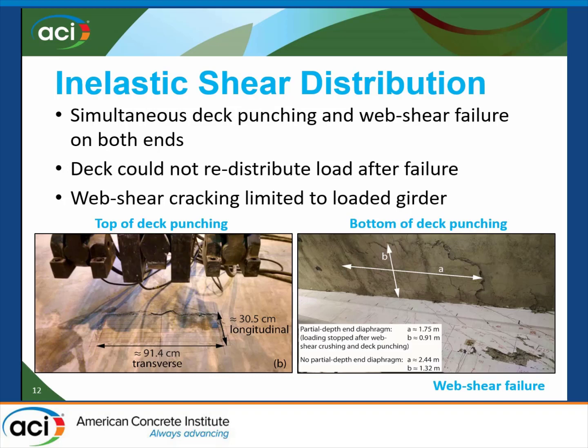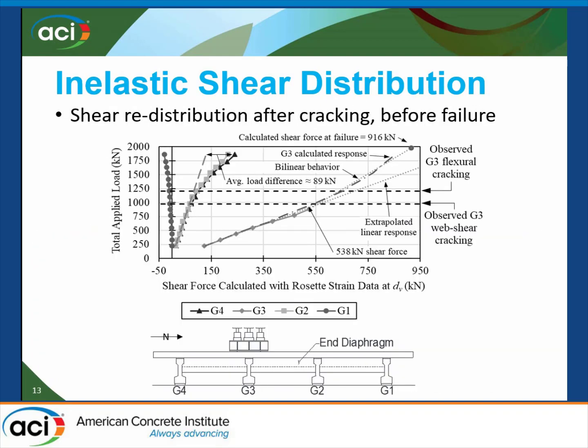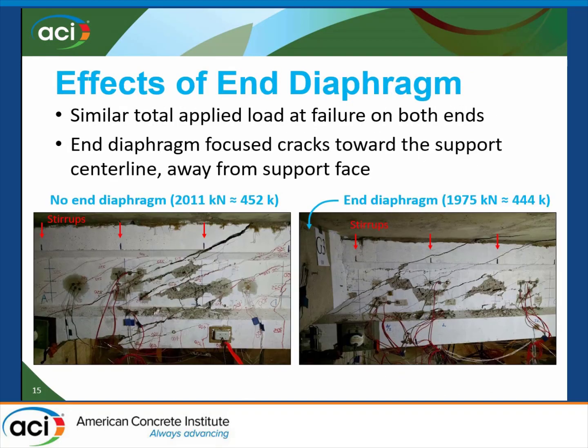So to follow up on that, how do these loads compare to the actual wheel loads that would be applied to a bridge deck? Sure, great question. They're significantly higher. An axle load in the US code is about 32 kips, divided by 2, 16 kips. This point load that we went up to was about 450 kips in one spot, so vastly different. So there's a huge margin of safety in that regard, which is also talked about in the paper behind this. But yeah, this is really trying to investigate what happens after elastic behavior.